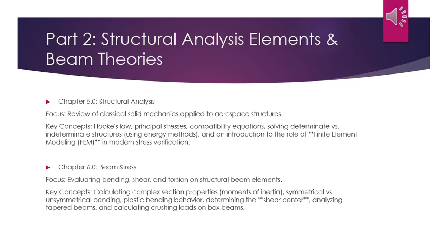Chapter 6 is about beam stress. It focuses on evaluating bending, shear, and torsion on structural beam elements. The key concepts are calculating complex section properties, moments of inertia, symmetrical vs unsymmetrical bending, plastic bending behavior, determining the shear center, analyzing tapered beams, and calculating crushing loads on box beams.